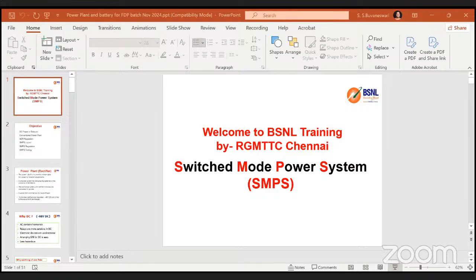The answer is, we are generating alternating current and we prefer to distribute alternating current only due to the reason that we can minimize the transmission losses with the help of transformers. So that is the major reason identified by the distribution company, so it has taken a decision that all the distribution and transmission has to be done in AC, so that with the help of transformers we can step up the voltages, so we can minimize the transmission loss. So this is the idea behind the transmission of power supply from the generating stations to the end users.